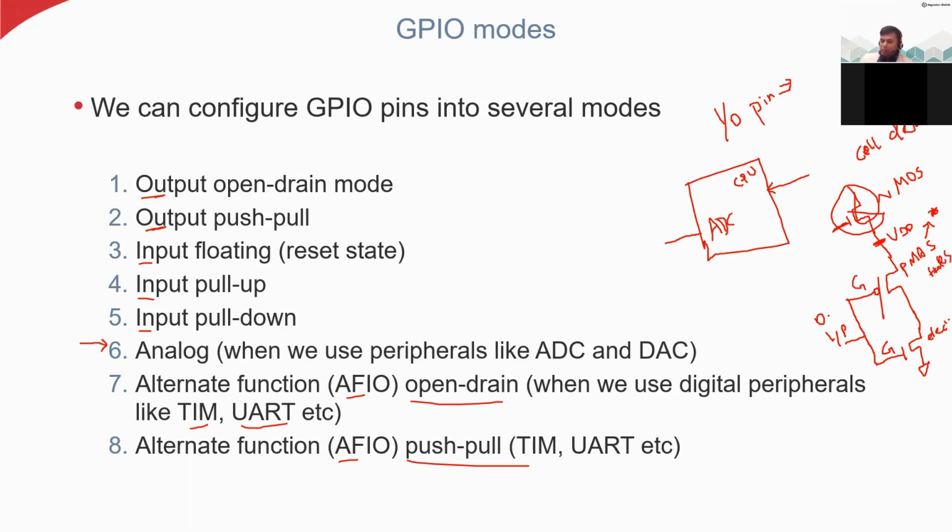So according to this, whenever you apply 0 to both inputs, this PMOS will turn on. So this VDD will travel through this source to drain, and then it will reach this part. And here the VDD cannot travel further down because this is open. This is short circuited because of the gate. Here it's open circuited, so we get the output equal to VDD.